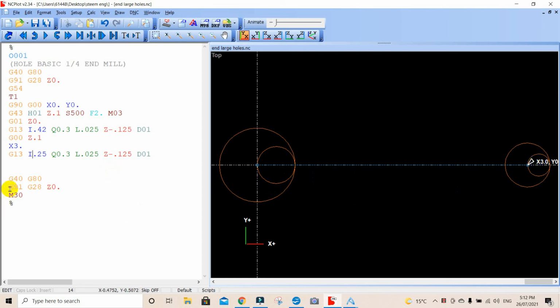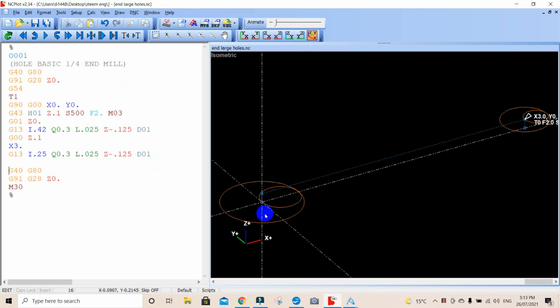So it will come along and cut that. By the way, if you have a space here, your CNC will just skip over the spaces. If you have a gap there, it doesn't matter. If you look at the end of my program, sometimes you've got things you don't want to see here. Remember, that's a rewind to the start. If I've got things I want to not see on the screen, I can always just type in M30 and you won't see it because it'll just end the program and rewind to the start, and do away with all this rapid traverse at the end of it.